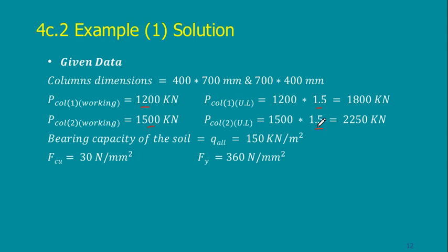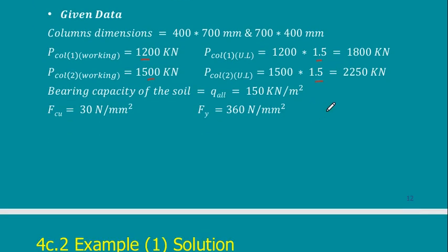Later, when our codes are unified and I have the soil mechanics code dealing with ultimate loads, in this case, I will use only the ultimate. I don't have to use both. So please concentrate now at this stage in both loads on where to use the ultimate and where to use the working loads, because it is a disaster if you use the same working load for the design of steel.